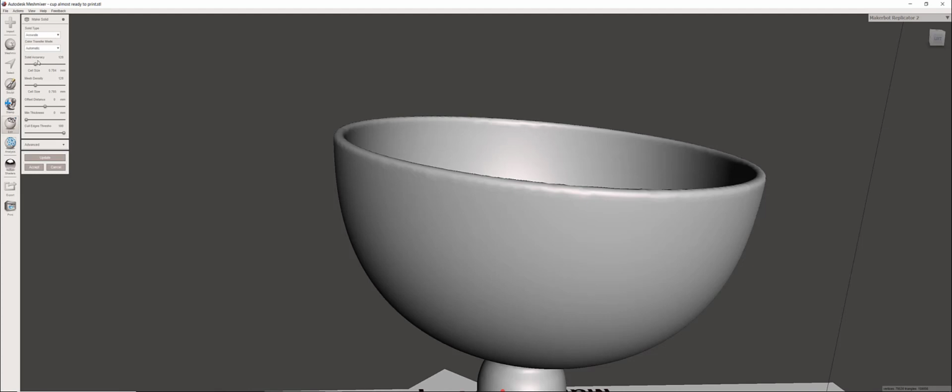Okay, it's accurate. And here in solid accuracy, we're gonna move this to the right. The lower this number is, the more detail you will have. So we can go to 0.4. Also, the more detail you have, the bigger this file is going to be. Okay. Also, mesh density does the same. I'm gonna send it to 0.4.